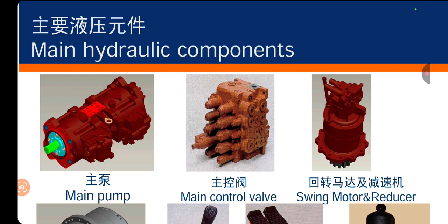Main pump's oil will not operate the spool. It will just get the direction from the spool. But the other pump which is sending oil towards the control valve will operate the spool so that it can open the way for the main pump's oil. Alright. Spools are actuated mechanically, hydraulically, and even pneumatically. Okay, there are electrically controlled spools as well, those spools which have solenoids for operation. So I think it's enough.